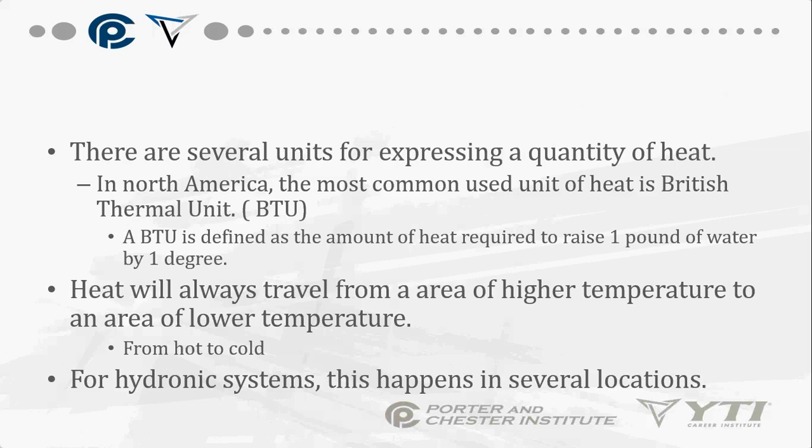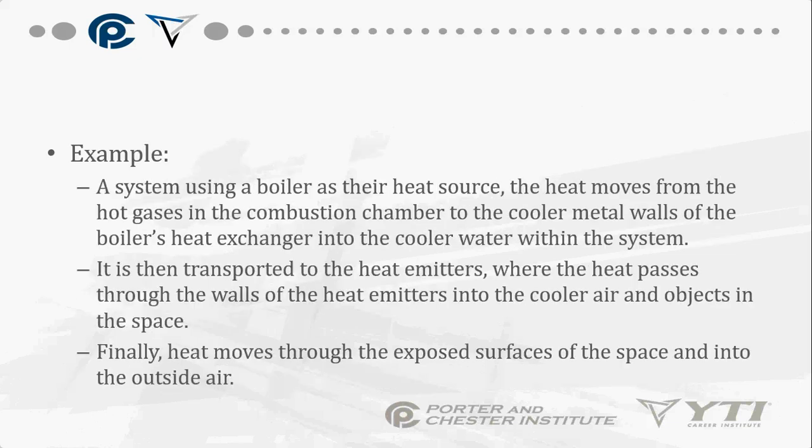Okay? Heat will always travel from an area of higher temperature to an area of lower temperature, or better known as from hot to cold. Okay? For hydronic systems, this happens in several locations. Our system uses a boiler as the heat source. The heat moves from the hot gases in the combustion chamber to the cooler metal walls of the boiler's heat exchanger into the cooler water within the system.